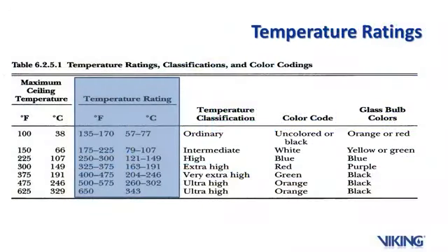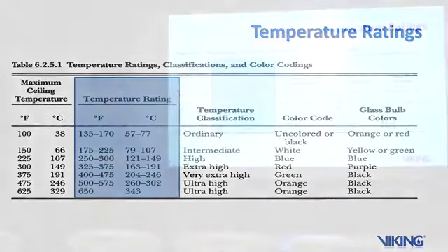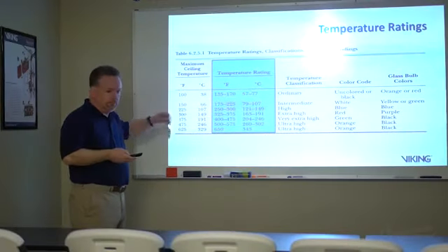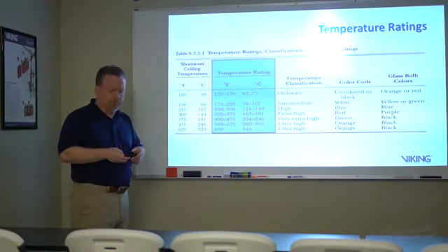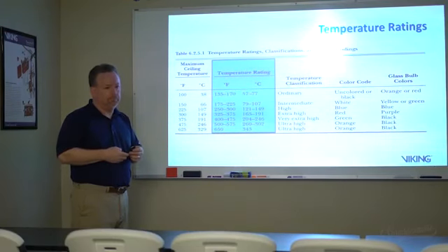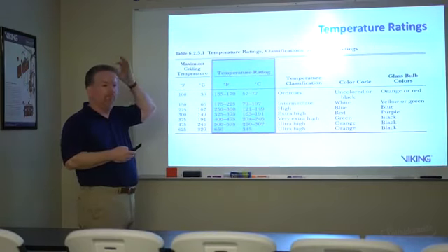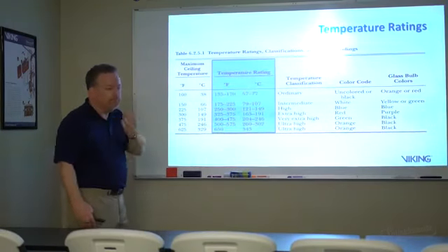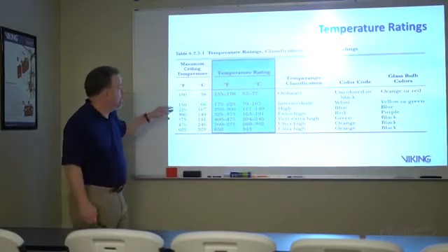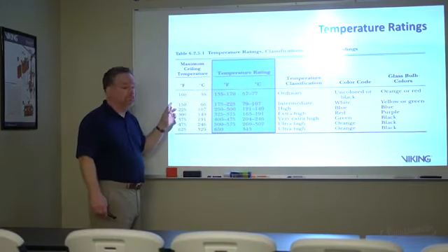Jim, we've even moved a lot down here and pushing very heavily through the engineer and design teams. Is the intermediate temperature as the standardized because of ambient temperature? Yes. And so that's one of the things that we've had to kind of consider down here. We realized even in an air-conditioned space, with the concealed head in particular, we're above the plane of the ceiling, and we're finding temperatures are very consistently over 100 degrees, even with AC below the ceiling. So we've made a very, very strong recommendation to everyone to go to intermediate temperature as their go-to sprinkler.